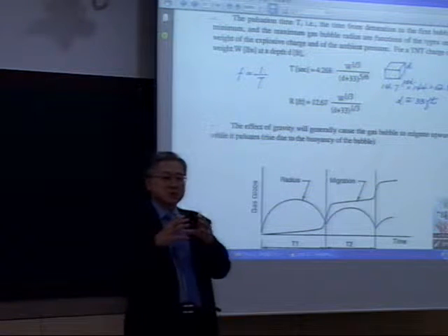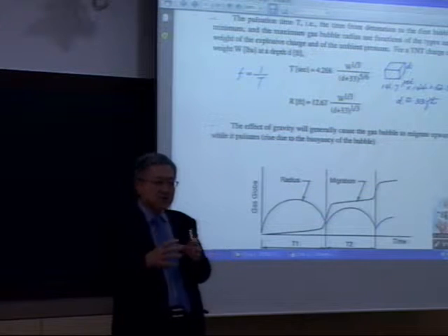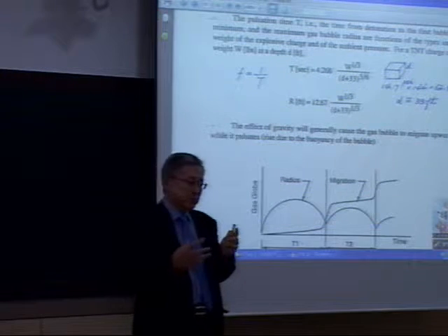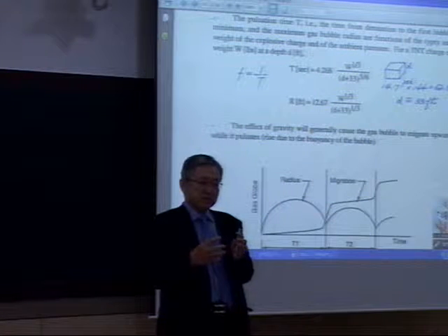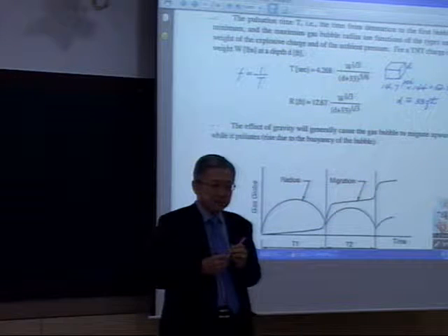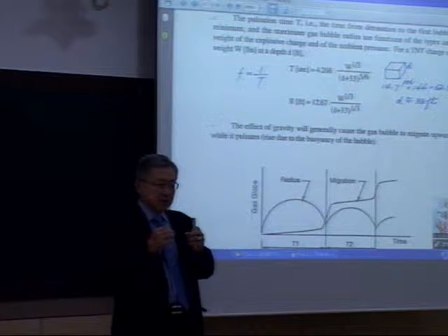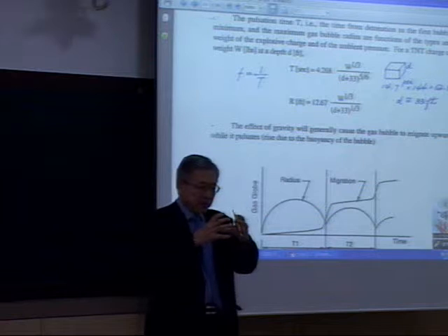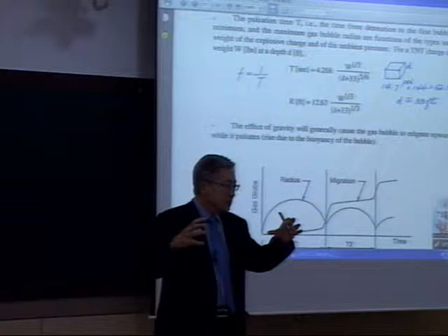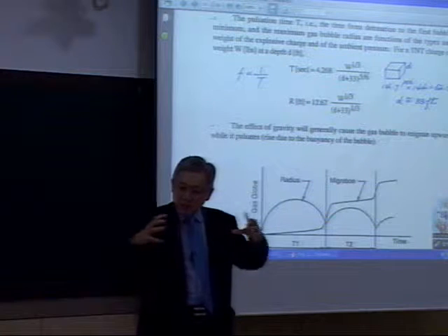That's the detonation speed. To really study what happened right in the vicinity of the charge at the time of explosion, or what happened inside the explosive at the time of detonation, you have to study detonation physics. This course is Naval Ship Shock Analysis and Design. Anyway, then the detonation speed converges down to what speed? Acoustic speed, which is about 1,500 meters per second. Then it propagates.